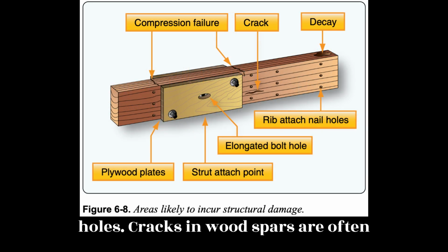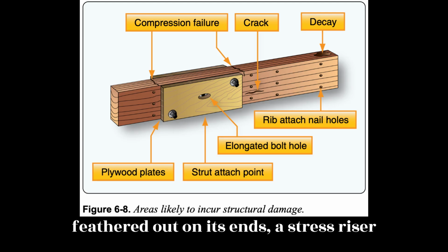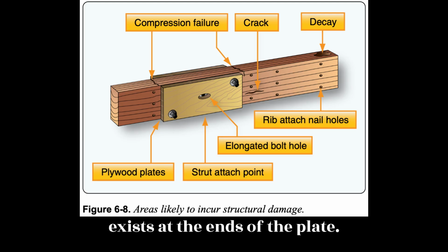Cracks in wood spars are often hidden under metal fittings or metal rib flanges and leading edge skins. Anytime a reinforcement plate exists that is not feathered out on its ends, a stress riser exists at the ends of the plate.